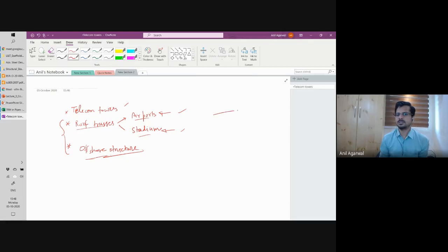One kind of system I have seen often is a 3-tube system, where the braces are provided this way, and these braces are even tubes sometimes, and there will be a weld between these braces. All this welding is done not at site but in a factory, where they can do it in very good detail.